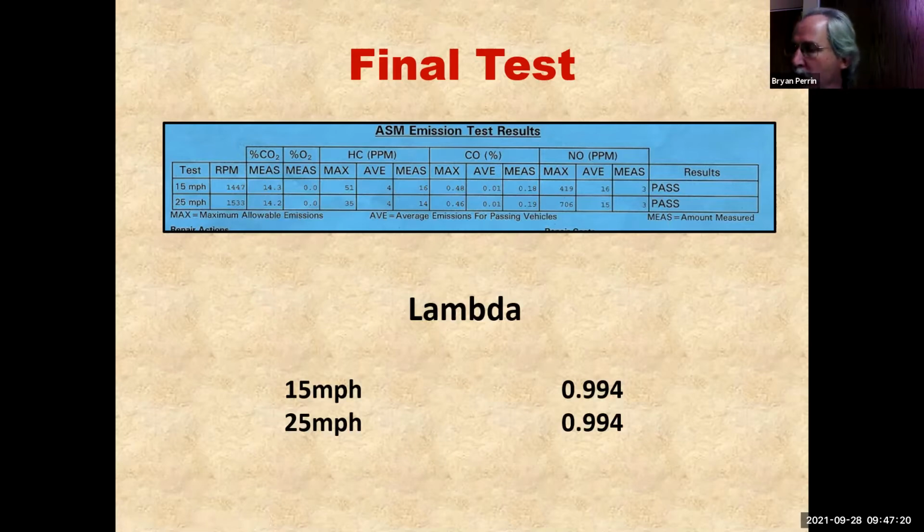So the other shop apparently read the description. Front O2 sensor must need one. Trim control makes sense now, doesn't it? This car uses rear fuel trim. Did I know that going in? No, I proved it by watching the relationship of the sensors.